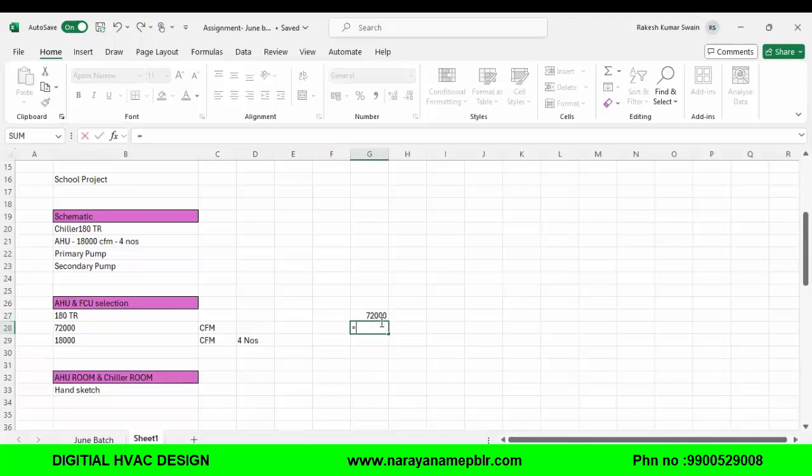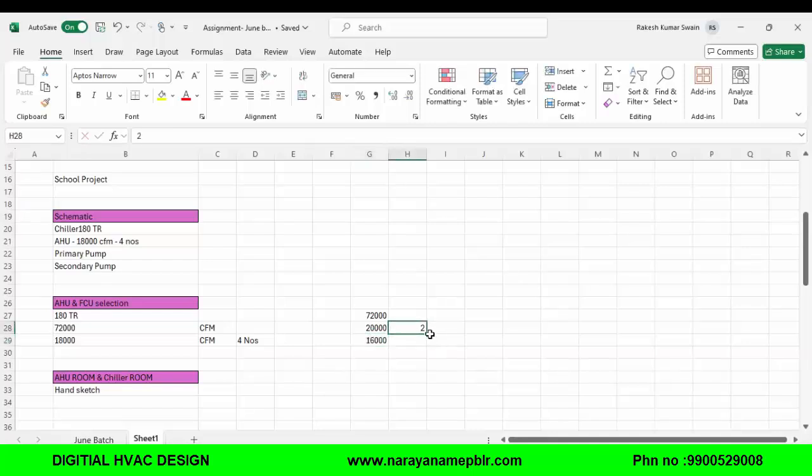Whether you select one number of 18,000 CFM, four numbers, or for example 20,000 CFM, 2 numbers, which is 40,000, remaining is 32, so 16,000, 2 numbers. That way also you can plan the configuration accordingly.